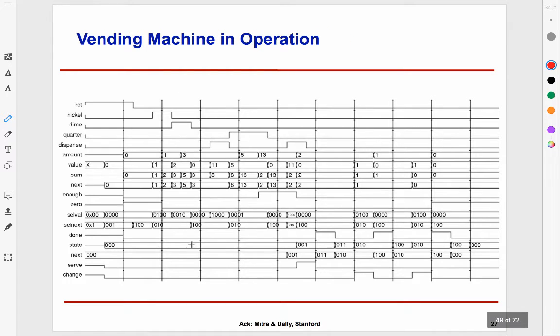And then finally, you will have to operate this thing. So when it comes to finite state machine and in Logisim, one key difference that will now happen is that you will be testing with a clock. There will be a clock which will be running and mimicking as if your state machine is running on every clock tick, and then you have to see whether the waveforms come out right or not. In this particular case, this is some sequence of scenario as it unfolded, and I'm just going to highlight a few key points out here.